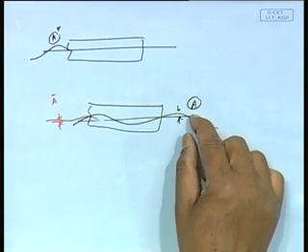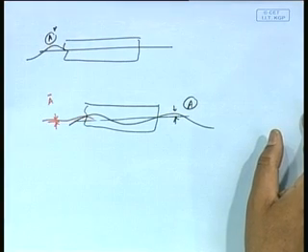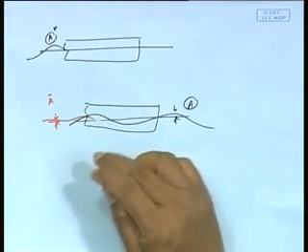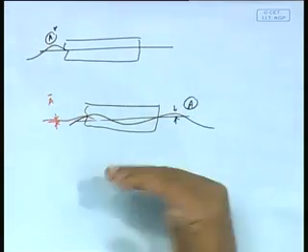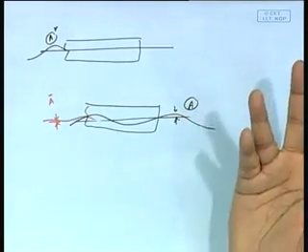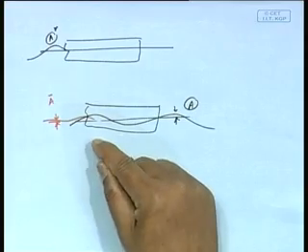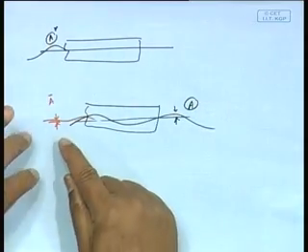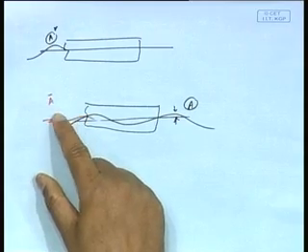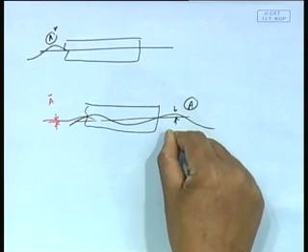Now, here is where we differ. In all other responses like vertical acceleration, motion, etc., the response was a linear function of A, but here my wave resistance or additional resistance is a quadratic function of A, and therefore, the spectral formula will not apply. So, because it is actually a square function of A bar, this is basically quadratically dependent on the incident wave.